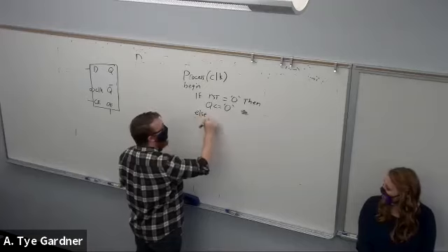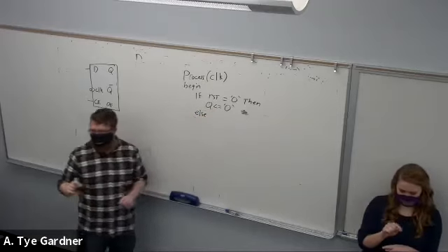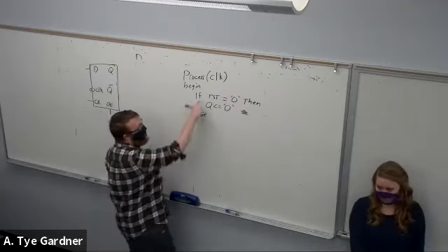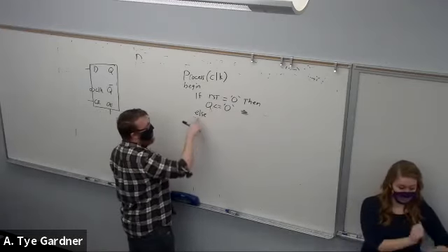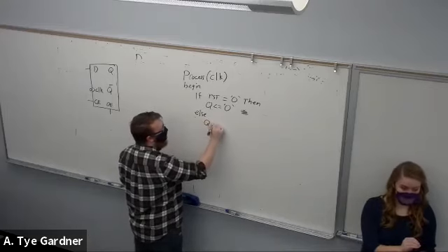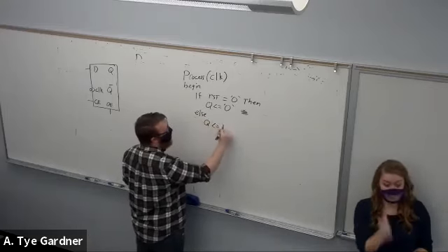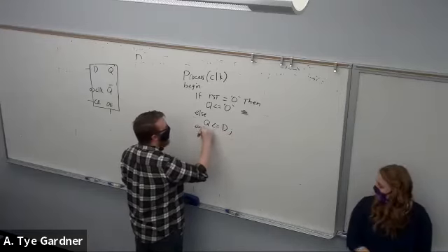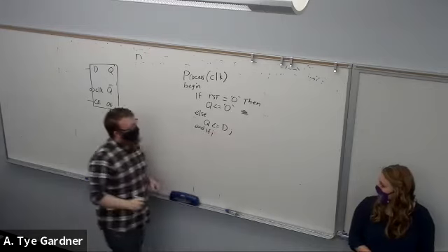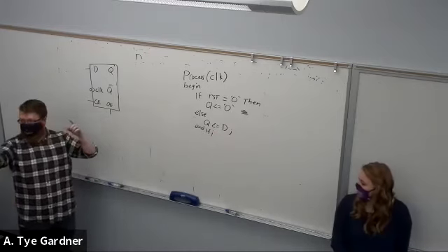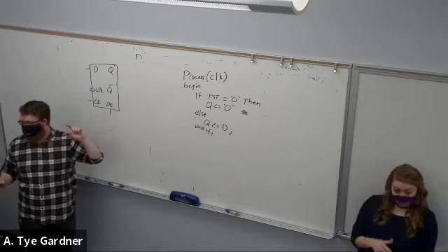All right, RST is reset, right? Yeah, RST is reset. So if reset is 0, then Q gets assigned to 0. Otherwise, Q gets assigned to D. Is this an active low or active high reset?